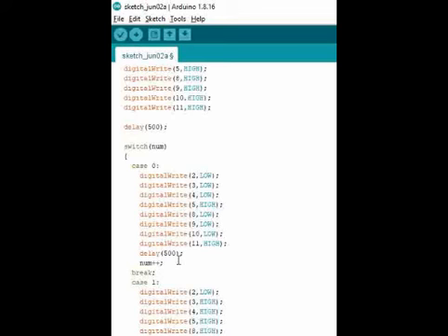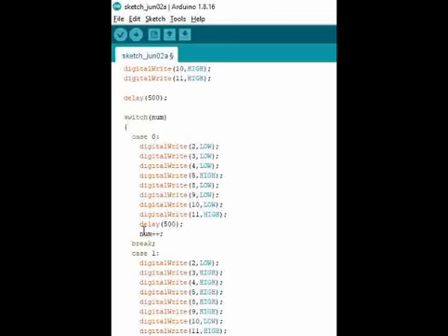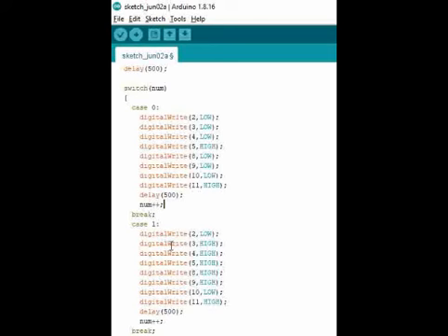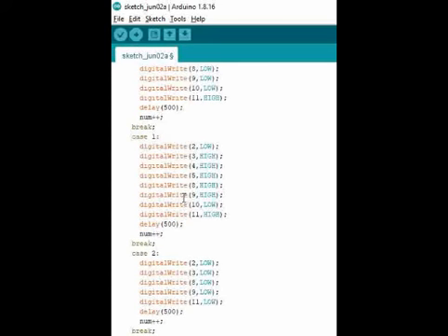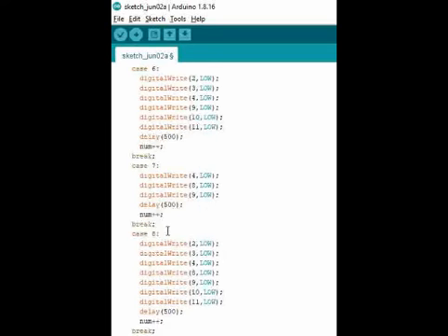And then we are giving a delay. And what we are doing is we are just trying to increment num, so that we are in a loop, and continuously the code runs. Once the switch case is executed and num is incremented, this breaks out of the switch case, and as it is a loop, it again comes here, the num value will be 1 and it goes to the next case. Similarly, again it is incremented here, and num becomes 2 after executing this case, and in the loop it comes to switch of 2, it goes here, so till 9.